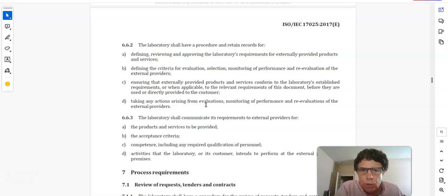That would happen for 2 main reasons. One, they gave you the wrong calibration certificate, and sometimes calibration vendors are a little tricky that way. They might even ask you for more money. But if you paid for an ISO 17025 calibration, you should get on the calibration certificate what you paid for. If you didn't, then yell and scream and get your money back or have them give it to you.